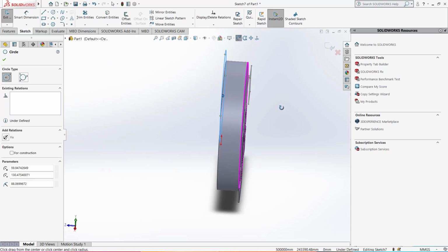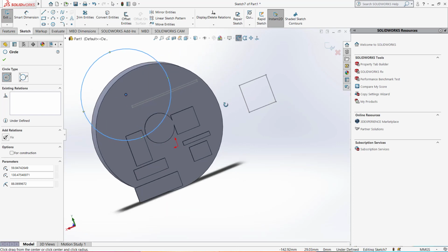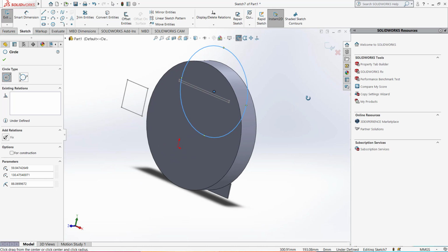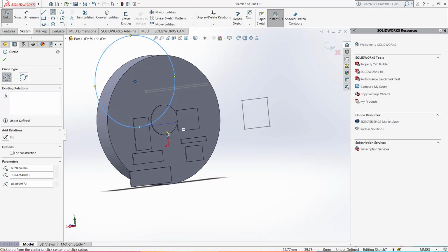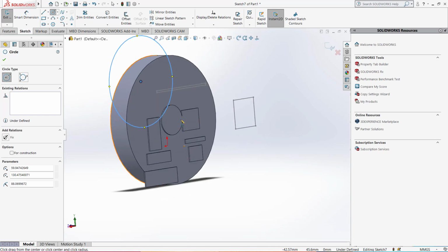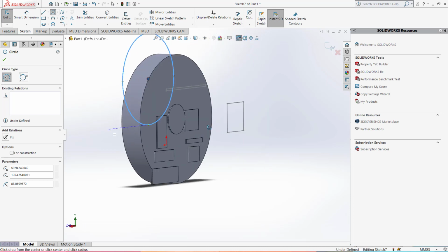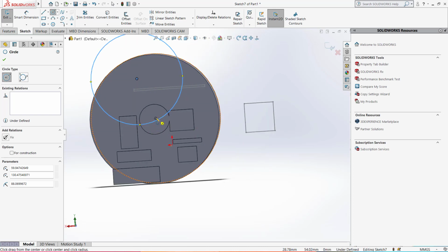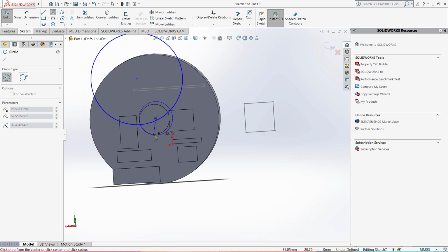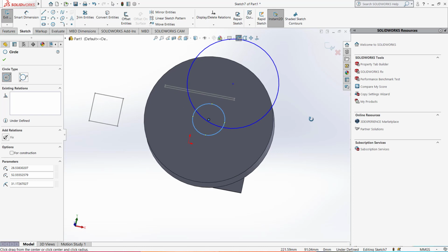Alright, so basically, SolidWorks gives you the chance to look at anything you're trying to look at in making your sketch. You can actually make reference to that particular thing in your sketch, but it's still going to appear at the front. So assuming I'm trying to make the same circle as is here, and then I want to make it on this surface, I can just turn here, come to the center of that circle, draw that circle, and then it's going to appear here. Alright, so this is how to engage the sketch tool.